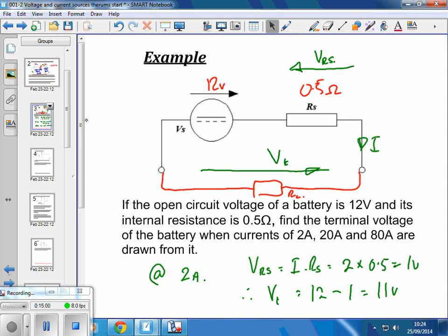So the only thing they can change is the strength of the magnetic field. So they control the magnetic field by varying what's called the excitation current on the rotor. Yeah, I mean, if you think of it in terms of this model, you are varying the internal resistance, yeah.